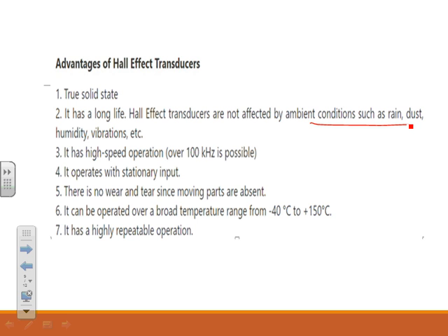It operates with stationary input. There is no wear and tear since moving parts are absent. It can be operated over a temperature range from minus 40 degrees centigrade to 150 degrees centigrade. It has a highly repeatable operation. So these are the advantages.